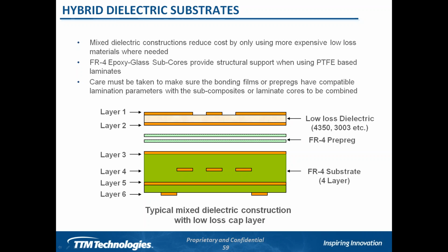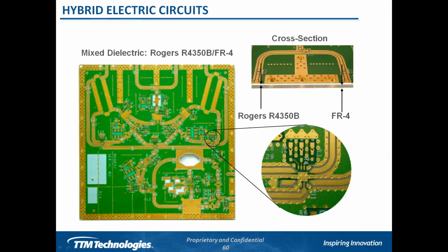And of course, what it also does is it creates some problems for warpage, but again, in some cases, you're constrained by having to go down this path for cost, so you need to live with a little bit of warpage in that final product. My example here just shows in the top right a cross section of a high-speed laminate on one side, and that would be an RF or a microwave type application. And then underneath, where you may not require the high-speed material set, you can have standard FR4, and we'll build that as a hybrid.